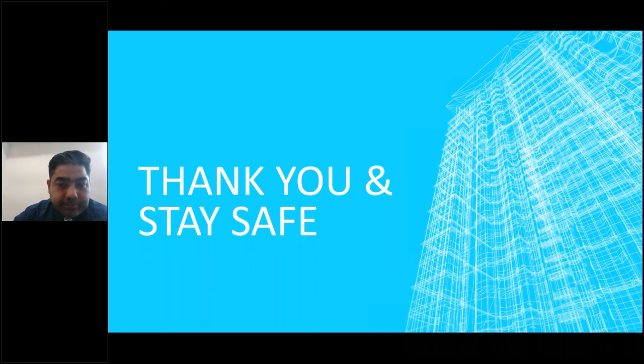Otherwise, you can have measures like no-cost measures put in place to understand what is the requirement versus what the boiler is producing. And from an operation and maintenance point of view, having better insulation, making sure the insulation is not worn out, there is no heat leaking out of the boiler anywhere, and also having your water tested regularly to see that the water going into the boiler is of good quality, or at least fair quality, so that there is no fouling expected.